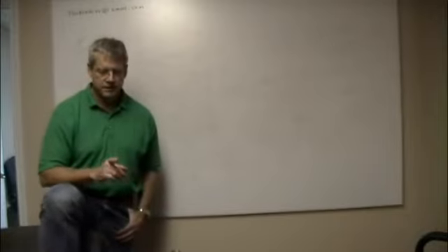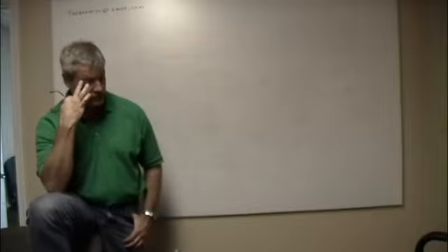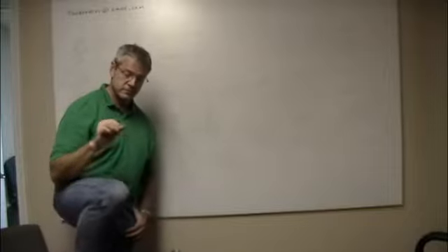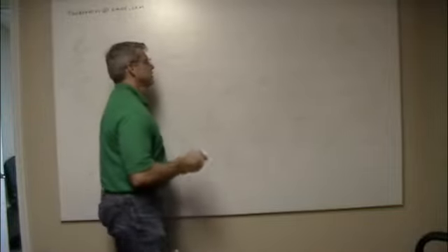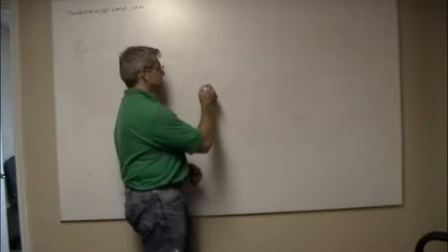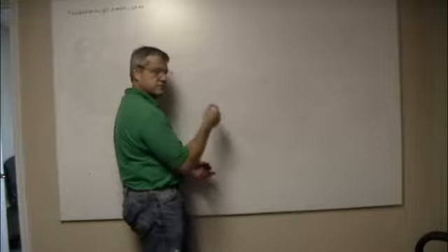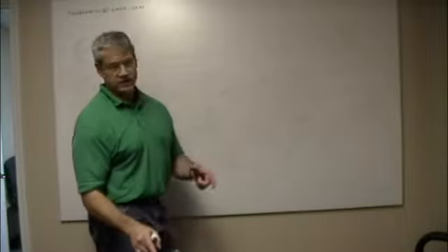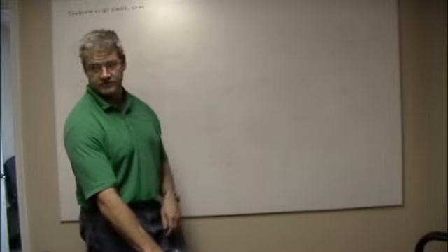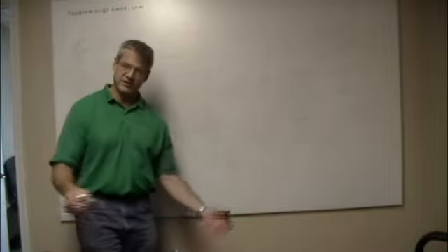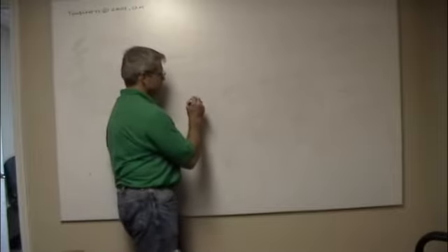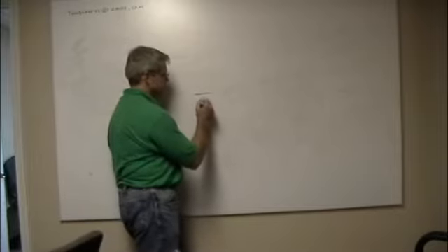One last thing, since we talked about caps kind of heavily tonight and using them for these kind of things. We'll talk about this next time, so send me an email to remind me. There are 2 things. There's a time constant, which says how fast, if I put too big of a cap and too big of a resistor on there, I'll press that button and an hour later it'll finally get high enough that the microcontroller registers it as a high. And then when I let off of it, it'll be another hour before it gets down to the point where the thing registers it. But this is sort of a safety thing.